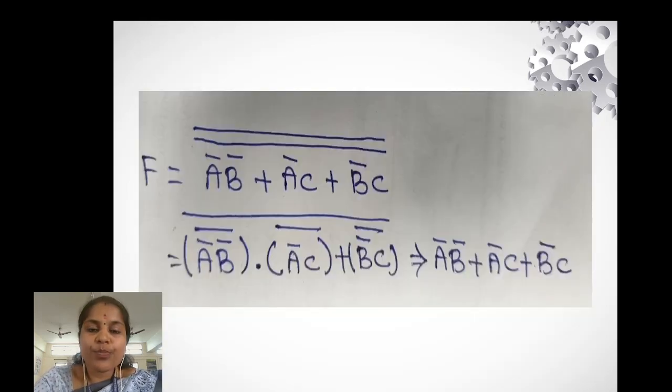Now, every product term is generated by a NAND gate. The outputs of these NAND gates are then fed into the final NAND gate. This produces the original function while using only NAND gates. This design is preferred in practical digital systems because NAND gates are inexpensive. NAND gates are very easy to manufacture. Larger circuits can be built using a single gate type. Troubleshooting and fabrication become simpler.